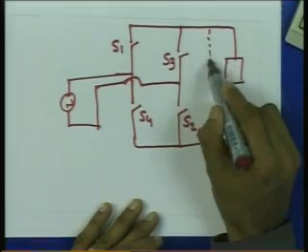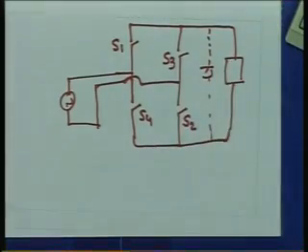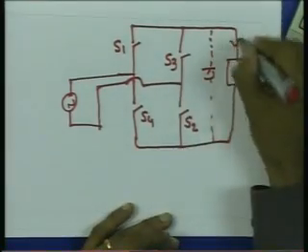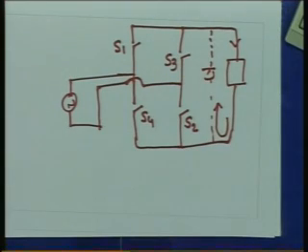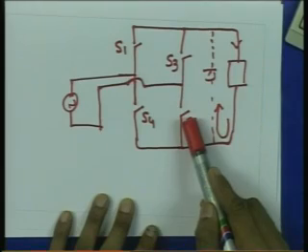But the control scheme or the switching technique says that open S1 and S2 now. So, if I open S1, S2, either have a freewheeling diode across the load, because the moment I open S1, S2, current freewheels to the load, it was flowing in this fashion, now it will flow through the diode, what is known as the freewheeling path, or I will not open S2.